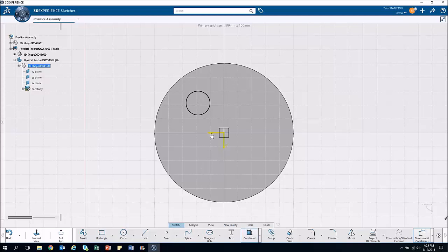And I'm going to double click on this constraint tool, which just keeps the constraint tool active while I'm working here. So I hit 20. Now notice it's still active. I don't have to go down and pick it again from the menu. Set both of those in. I'm just going to do both of them at 20. We'll give this a diameter of, 17 sounds pretty good.